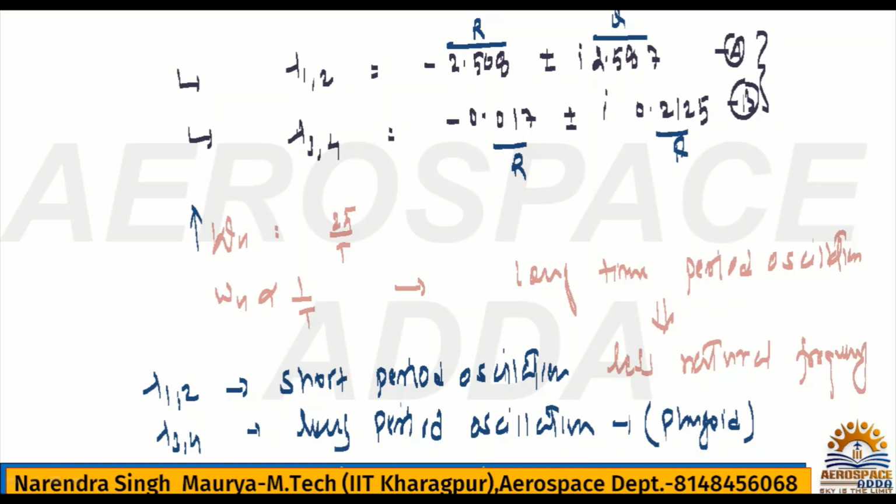Damping is basically defined as continuous reduction of amplitude. And if it is short period oscillation, it means damping is very high. For that reason, oscillation is very short. Okay, so short period oscillation means very high damping ratio. So in that way also you can say the real part will be very high if damping ratio is high.